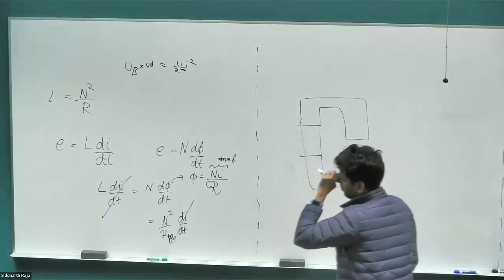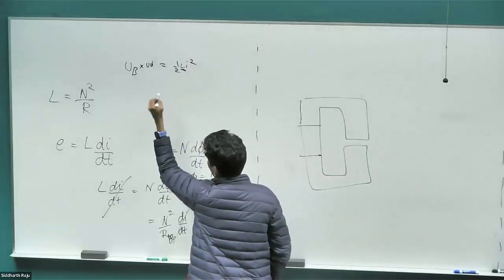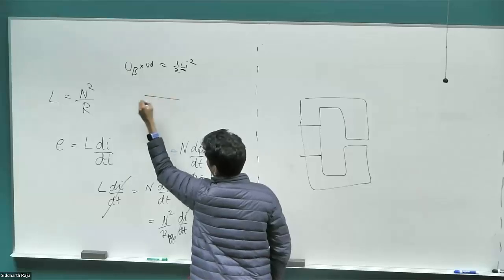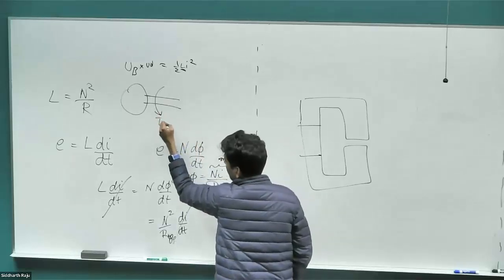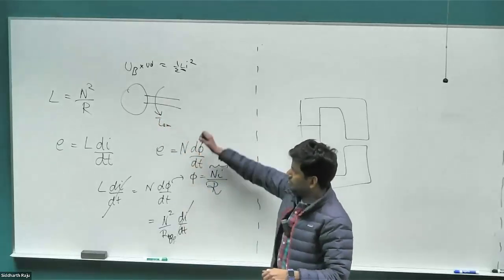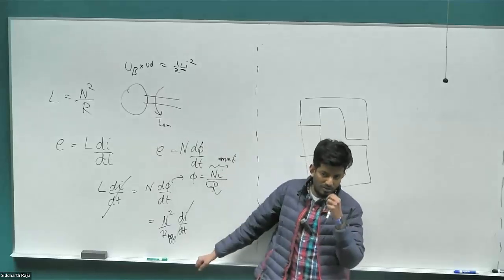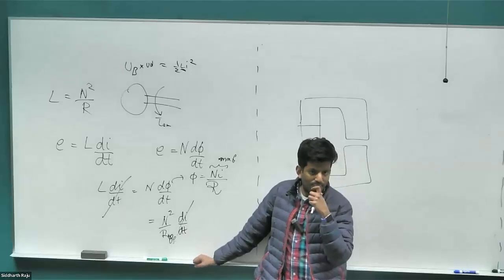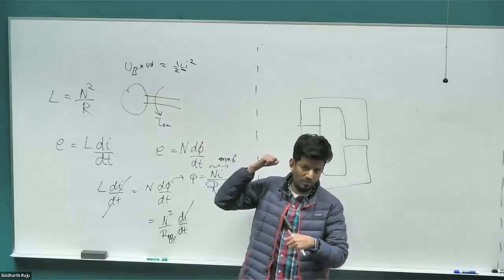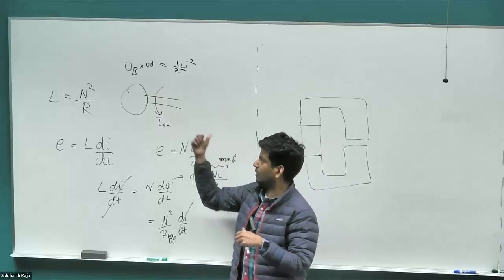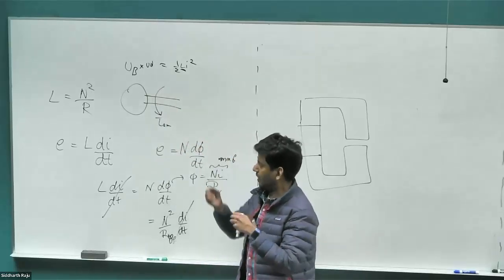So before I forget, sorry, there's one more thing that I want to talk about. When we talk about torque and so on in our mechanical system, when I drew this diagram, I drew the torque like this. This is a convention we use in motors. This is not a physics convention. In physics convention, what will be the direction of the torque? Okay. So if the system is rotating like this, the perpendicular direction is the direction of the torque. All right, that's the vector. If you are drawing a vector for the torque, it's actually this direction coming outwards, because your hand anti-clockwise is considered positive, so that will be the direction.